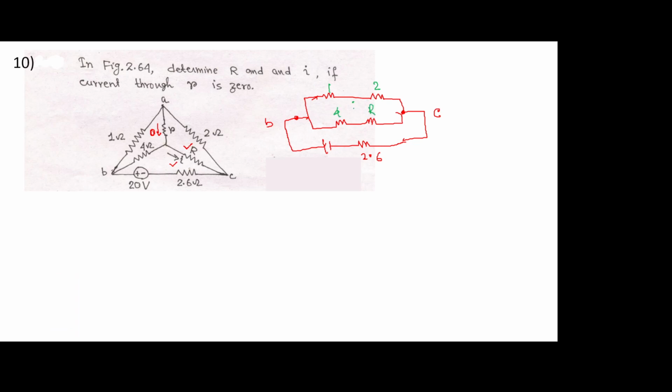This is unknown. Now those who are very new to electrical engineering probably may not have come across this, but those who are in their second or third year might know the Wheatstone bridge principle, right? This bridge is said to be balanced if the ratio of the resistances across the two branches are the same. That is to say, from the Wheatstone bridge principle, we get this.